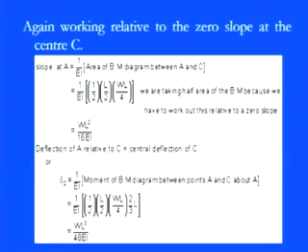But if you remember that part, there were really bulky equations, and we put certain conditions in to get those values. Here, it is pretty easy to calculate by simply going with the bending moment area and the first moment of area for this particular bending moment. In these two examples, the loading was pretty simple. That is the main constraint for this kind of thing: the loading must be simple so that we can get a straight feeling about the bending moment diagram, and then we can calculate.